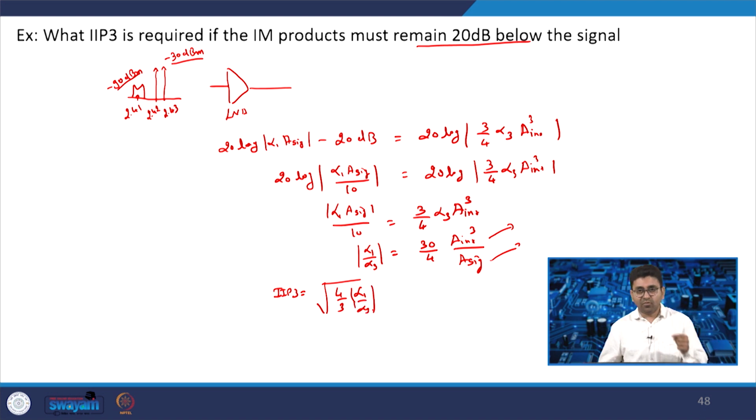So, in order to find the requirement, you need to know what kind of interferer is coming, and we already discussed when we were discussing the basics of wireless communication that all the standards will specify the blocker levels also, that is how much blocker level you need to reject, and here the interferer information is also provided in the IEEE standard. So, when you are designing any receiver, you should know beforehand what linearity we are targeting.